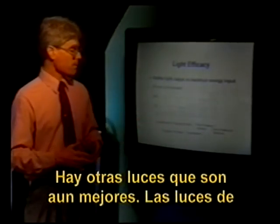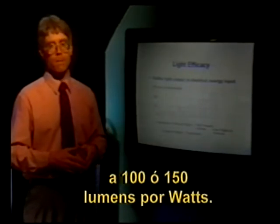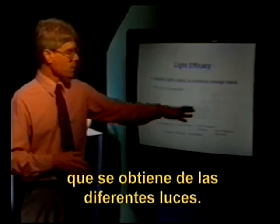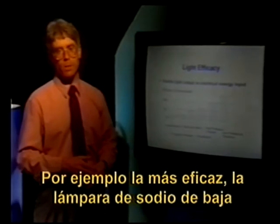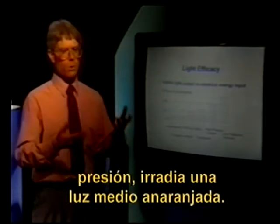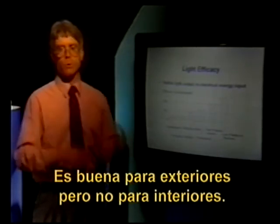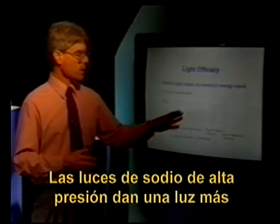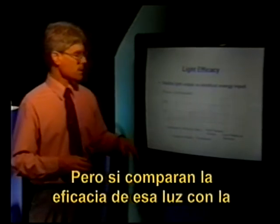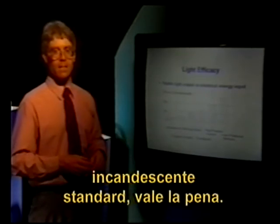There are other lights that are even better. High-pressure sodium or low-pressure sodium lights operate at 100 or 150 lumens per watt. You have to be careful, though, and look at the light quality that you get from different lights. For example, the most efficacious of these, the low-pressure sodium lamp, is a light you might have seen that delivers an orangish glow. It's good for outdoor lighting, street lighting, and so on, but not good for indoor lighting or reading. It would only be appropriate for certain outdoor applications. High-pressure sodium lights give a more white light, but it's still a strong, harsh light. But compare the efficacy of that light to standard old incandescent lights, and it's well worth it.